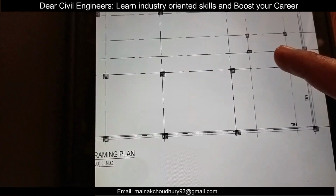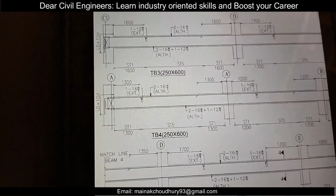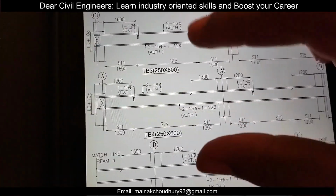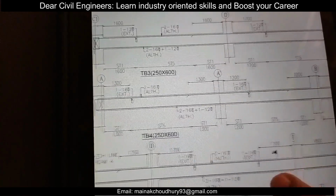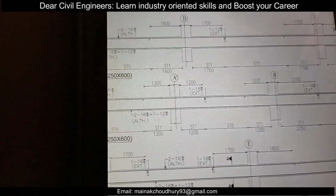So for example, this particular beam is TB4. So let's find out the foundation details provided for TB4 in the drawing. TB4 size is 250 x 600. As you can see, the width of the particular beam is 250 and the depth will be 600, and the reinforcement is used here. As you can see, span by span it has been given, and also the extra rebars have been given very accurately in this particular drawing.